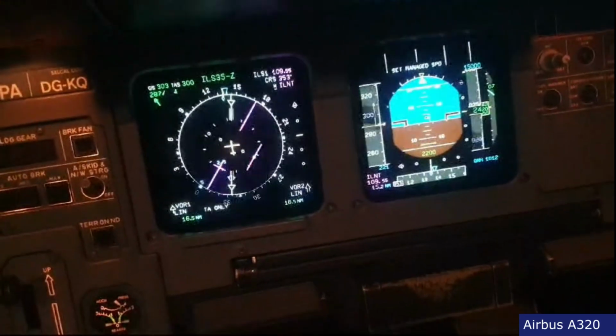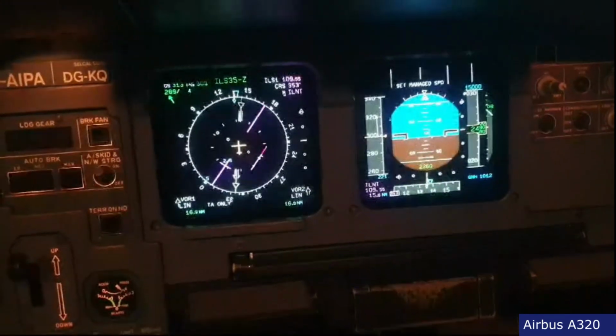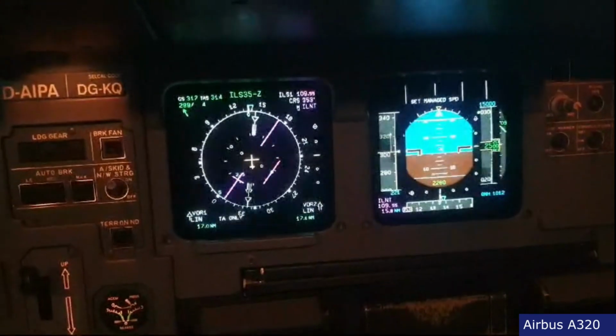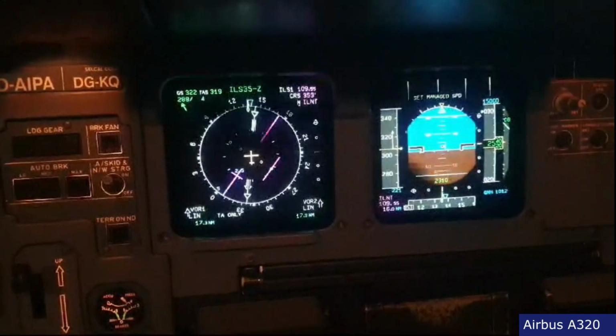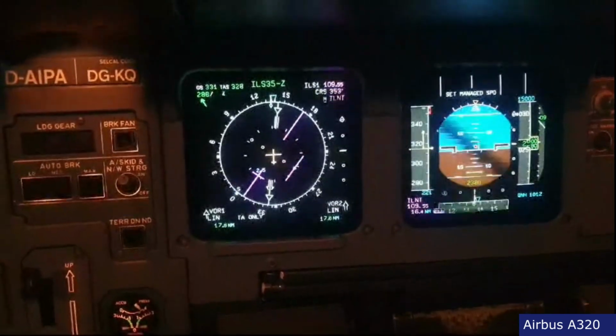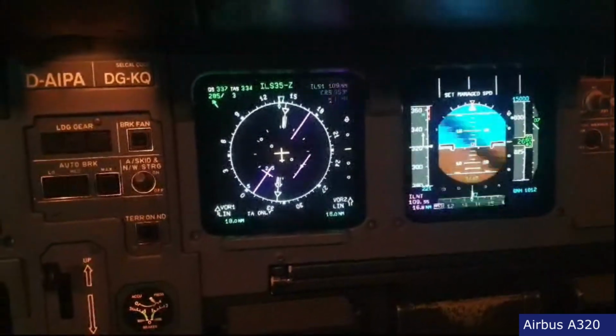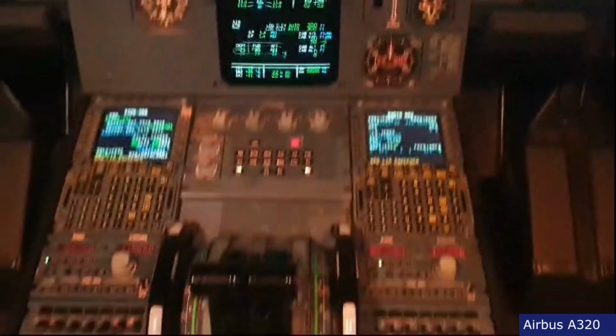Well, the fact is that the Airbus logic is not really a spare autopilot. As we say, the flight guidance computer is much more complex. It does not take just one item, like the vertical gyroscope, as a reference. What we're tracking here, yes, is the attitude, it's constant attitude, but it's also compensated for constant G.